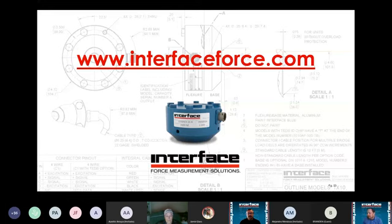Anything to add on that, Keith? I'd say these load cells are great for hundreds of hertz. You're not talking tens of thousands of hertz. They're not. So there's definitely a spot where, at very high frequencies, these kinds of load cells don't work very well. But most of our typical testing customers who are applying cyclical loads to a test specimen, low profile or strain gauge based load cells work great.